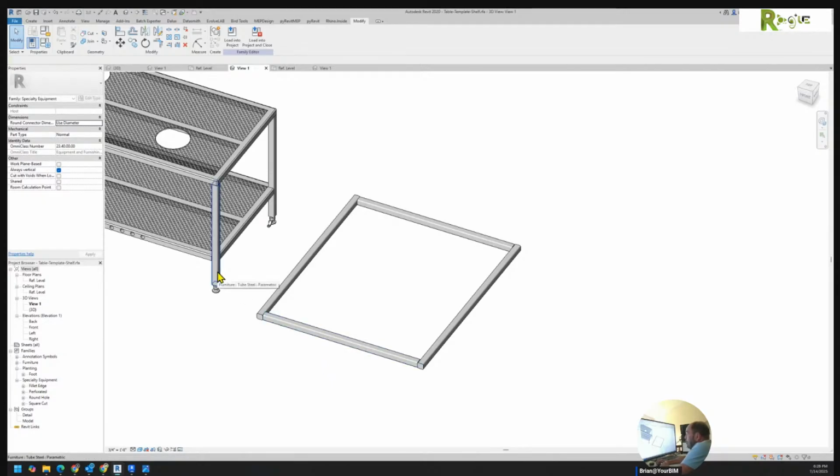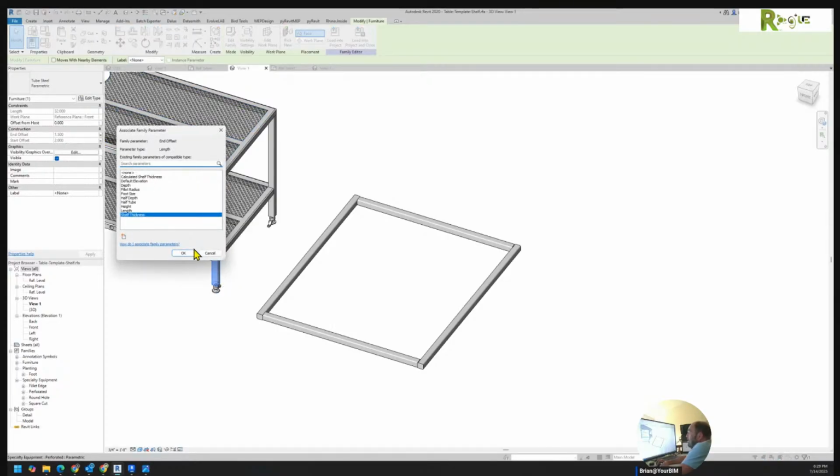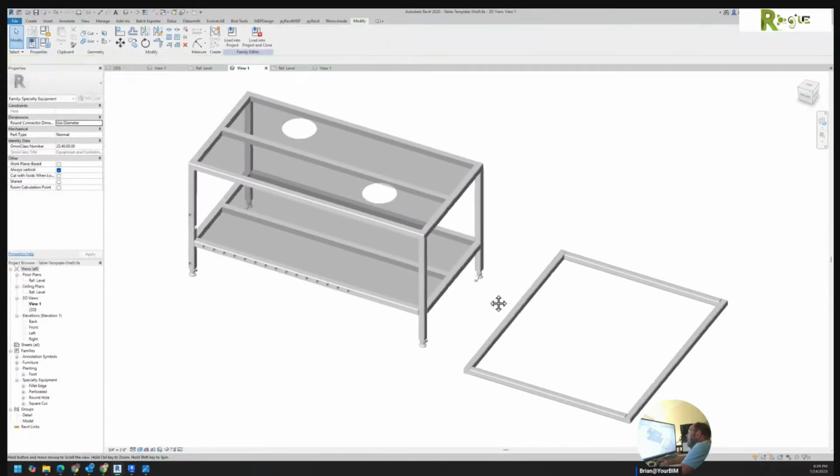Now you'll notice those 2 end offsets I was just talking about being 1.5 inches. You'll see that what I actually did was the one end offset, I wanted it to be related to my shelf thickness, which I've now called structure size, just so it wasn't confused. The idea being this offset, if I change that thickness, if I change that parameter, all this stuff grows. This needs to cut back. This cut needs to get bigger. All of that ends up happening.